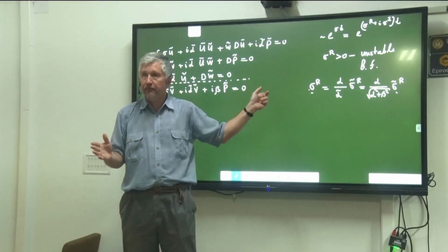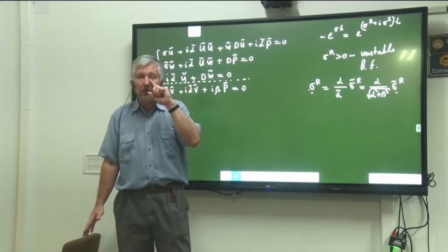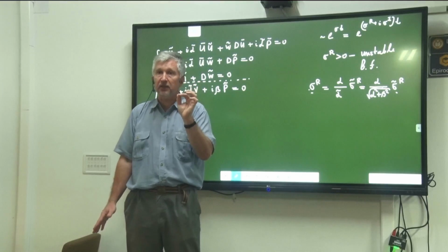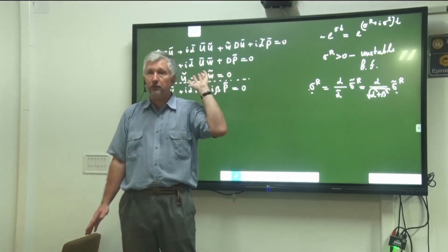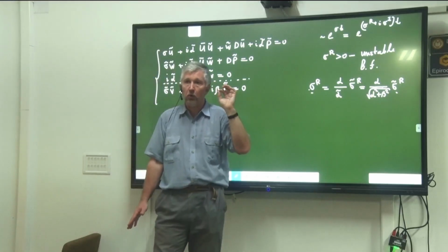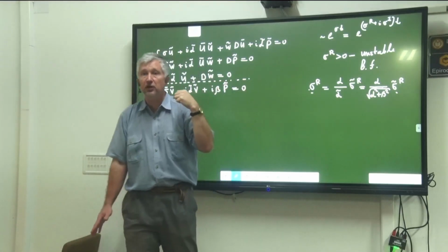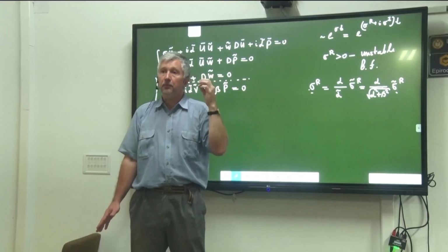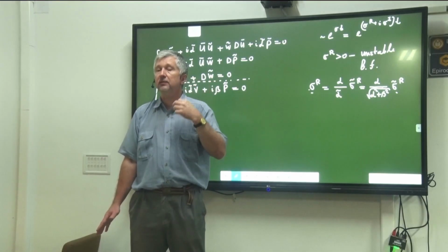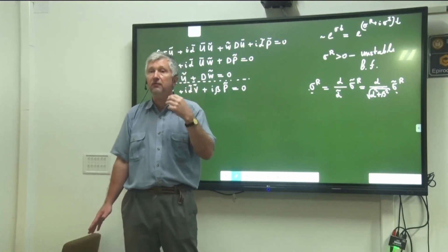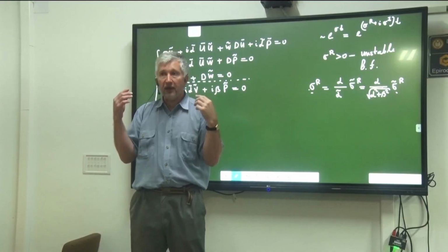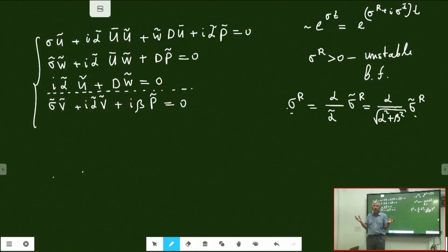And this is a very powerful conclusion, which is known as Squire's theorem. It is stated that for the flows that we considered here, U is the only non-zero component of the base flow, and it is essentially a unidirectional flow. Then perturbations might destabilize it first only if they propagate in the same direction as the base flow. So we don't really need to consider three-dimensional flow.